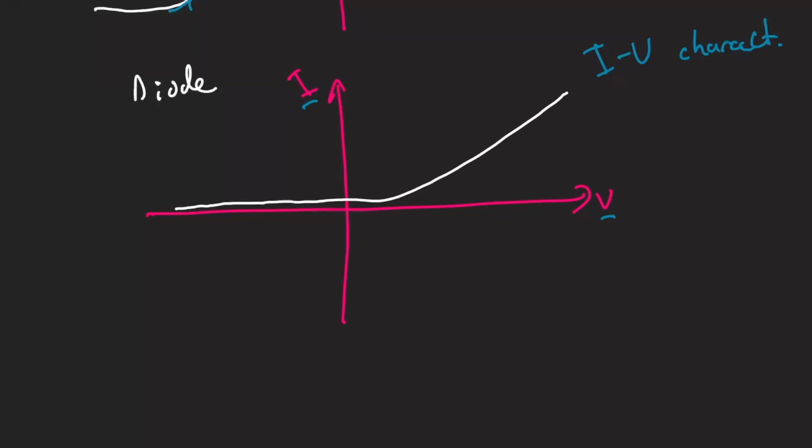You can see once you hit a certain positive potential difference over here, you get a regular current flow, and actually this looks like an ohmic conductor. Again, it looks like a pretty straight line. But over here, once you get towards a negative voltage, the current no longer flows and your resistance is no longer constant. You actually get a very, very high resistance if you try to have a negative potential difference, and that basically means that the current only flows when the potential difference is positive.